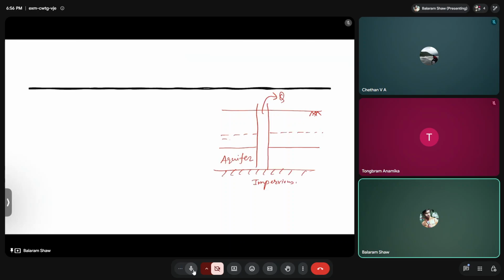There will be a drawdown in the water level. So the water will become somewhere like this, because water will flow something like this from all the directions, and hence the water table which was here will go somewhere deeper because of the pumping that is happening. And this is mostly given by the yield depression curve, which will show the drawdown that increases faster than the well discharge.